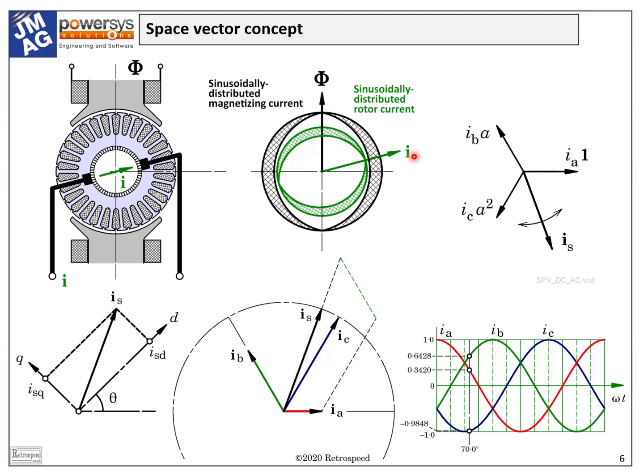Such a distribution represents the fundamental behavior of the windings of an AC machine, and the two parameters, I and the direction, are components of what we call a space vector. We will see that there is a space vector for each phase winding, and another space vector that combines the effects of all three phases. In the induction motor we will find a similar set of space vectors for the rotor as well.